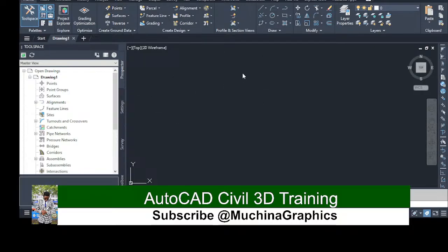I will click here, Import Points. I will come here, and this will show up, and then I click the plus sign and select the points that I need. So I select the topo survey points, and then I open, and then they will load.